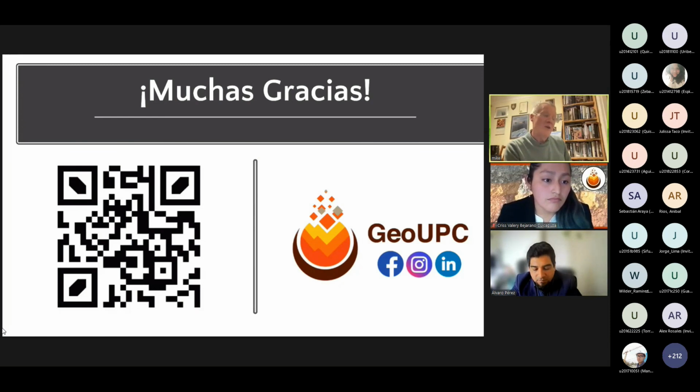Again, the first recommendation is go for that principal stress rotation paper, because that's where we set out how NorSand is extended to do cyclic mobility. And that tells you the parameter to pick up, and that is what you'll find in FLAC. I don't believe it's been implemented in any of the other software. I'm not sure about RS2, but Plaxis certainly doesn't have the cyclic one in.